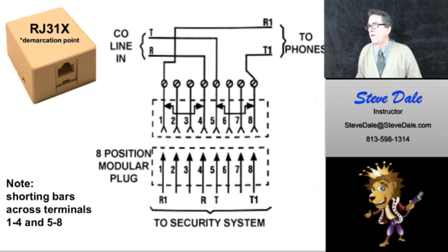Why do we drag that phone line through our fire and alarm panels? Well, first of all, we have to dial out through those phone lines, but we're supervising that phone line. So if the alarm goes off, the panels disconnect the house phones and seize the dial tone and communicate that way, so that nobody in the house can pick up the phone and disrupt the signals going out to the central monitoring station.